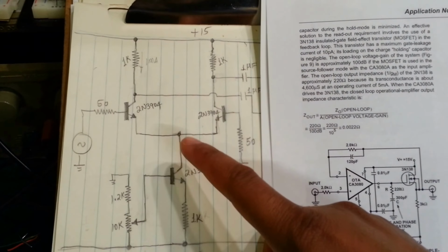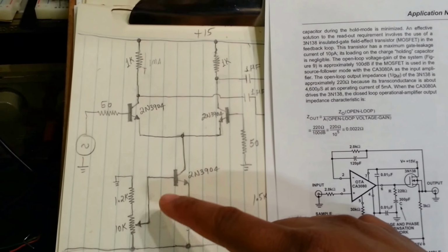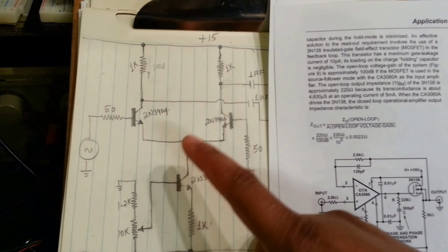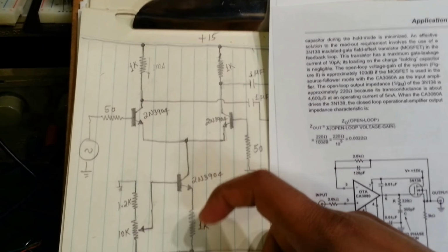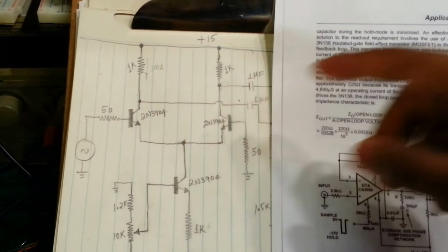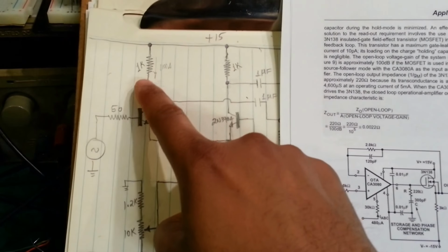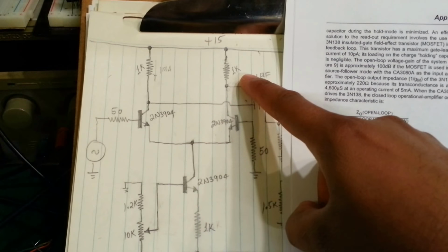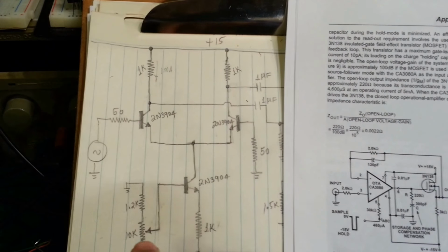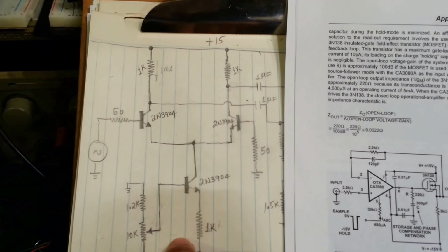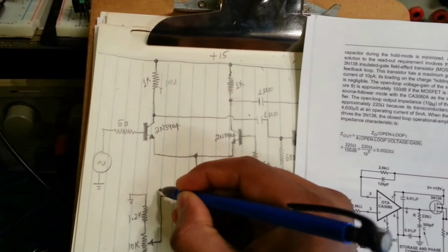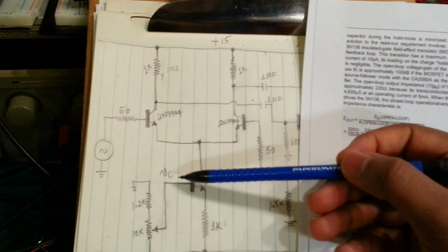which will ultimately modify the gain of this amplifier. I have shown a similar design in my previous video of how to design the current source part, to allow a certain amount of current to sink from the differential amplifier and to select these resistors. But for this question, we're given this resistor and this resistor, so we don't have to design that part. What we'll need to do is design the current source and also find the overall gain as a function of the controlling voltage, which in this case will be VC, this point here.